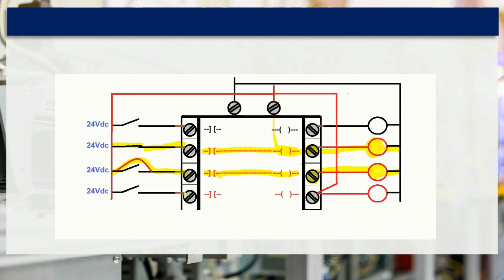The last switch, the switch is left open. Now somebody did some forcing before and wasn't paying attention, didn't delete them, doesn't matter, it's behaving differently. So as far as the logic's concerned, that is not true. This is off. I do not have continuity, therefore my output is not going to be turned on. But maybe someone was industrious and they went to the 24 volt supply and they ran a wire, put it on the terminal screw, bypassing the internal switching, and turned on my output.